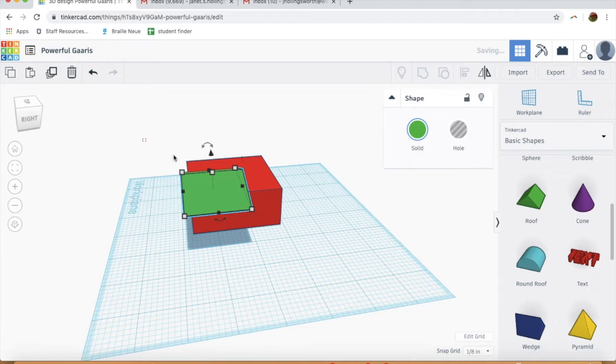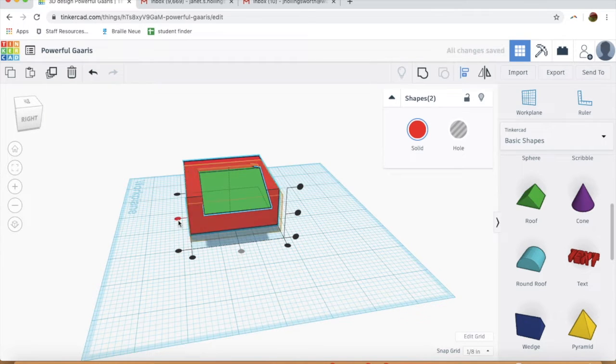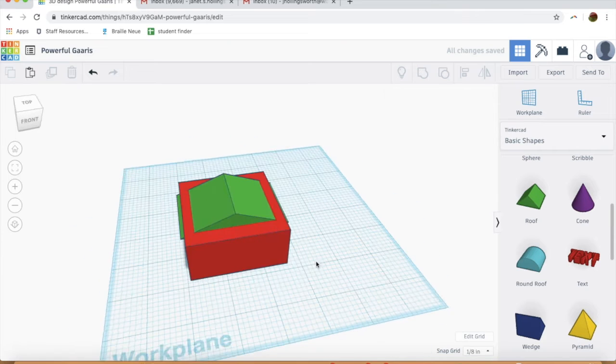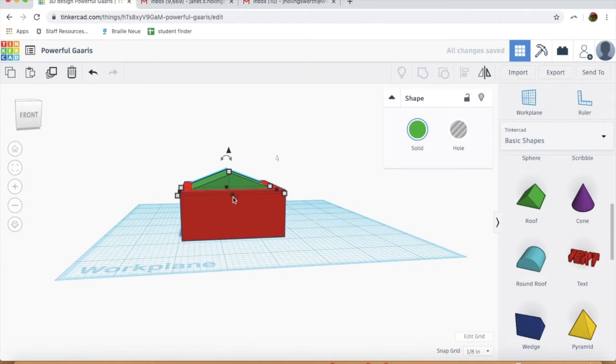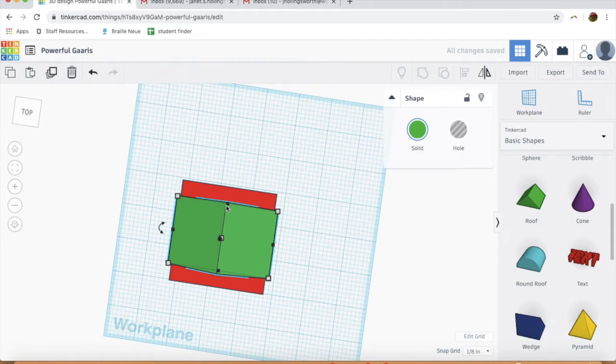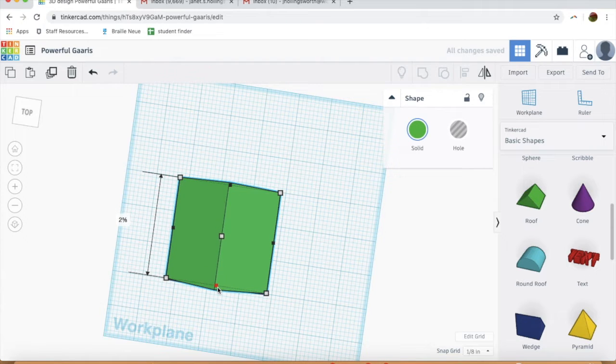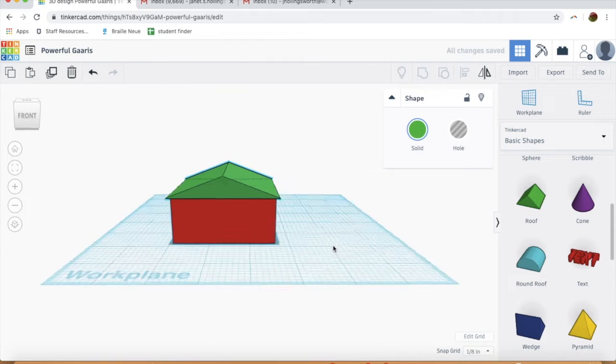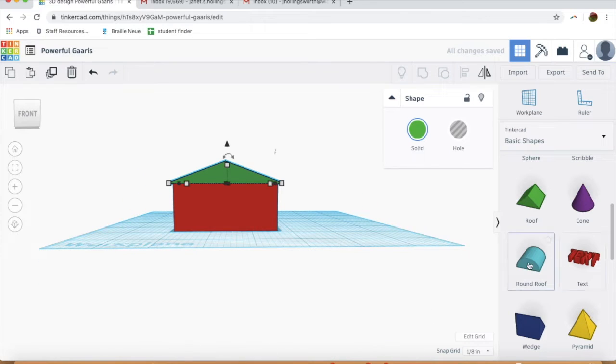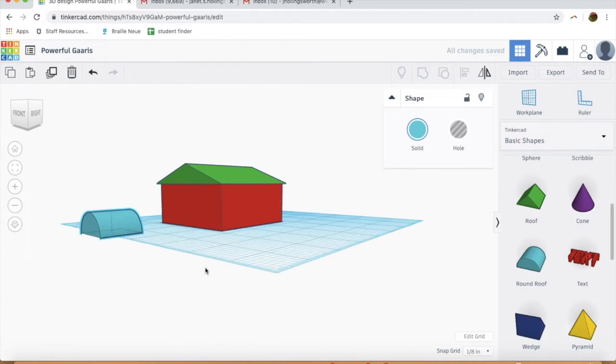So my favorite tip for that is selecting your objects, going up to the Align tool, clicking on those center pads, and then orbiting around and adjusting your object as needed. Again, remember that the command or control with the up arrow and down arrow allows you to adjust your Z direction. You can change your snap grid units down in that lower corner.